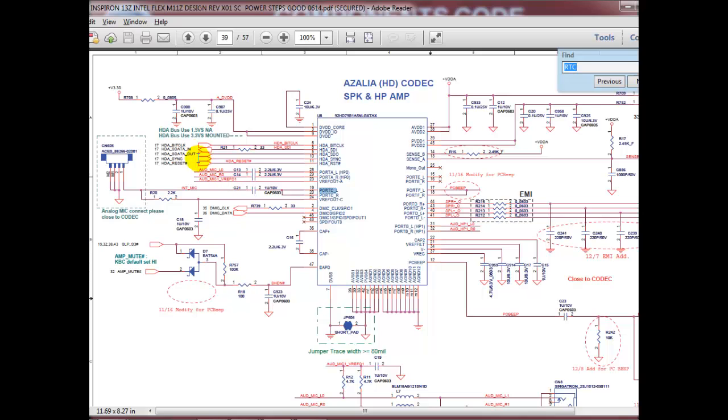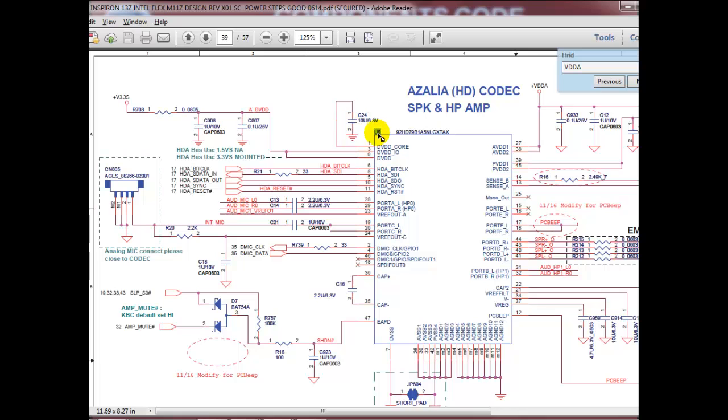If you want a particular signal, you can search it with the help of voltage. If you want Vin voltage, you can find it through the voltage, and it will show VDDA like that. On the motherboard there is an IC number, so you can search by IC number this way also. If you want to know U8, it is written on the board as U8, you can identify U8, and it will show the IC number which is there.